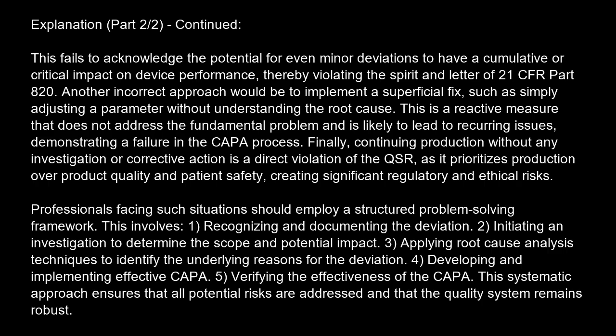Another incorrect approach would be to implement a superficial fix, such as simply adjusting a parameter without understanding the root cause. This is a reactive measure that does not address the fundamental problem and is likely to lead to recurring issues, demonstrating a failure in the CAPA process. Finally, continuing production without any investigation or corrective action is a direct violation of the QSR, as it prioritizes production over product quality and patient safety, creating significant regulatory and ethical risks.